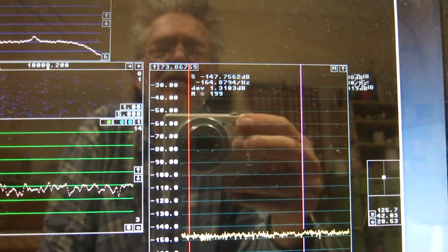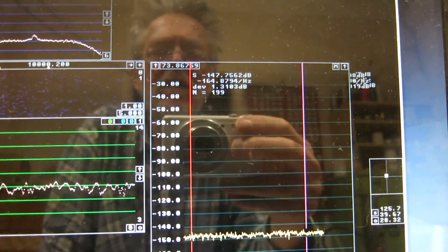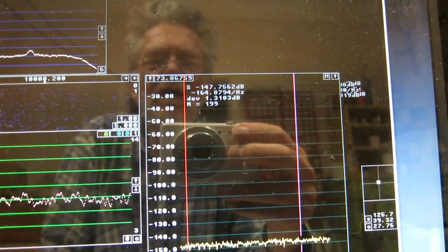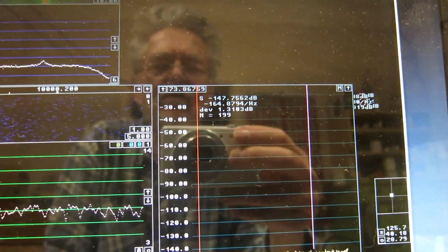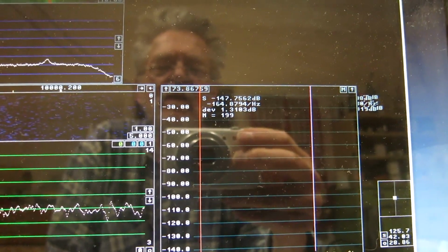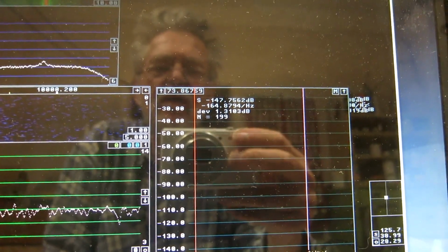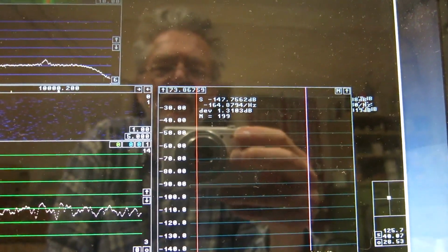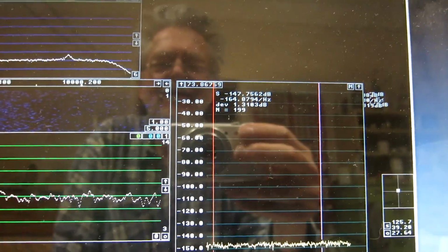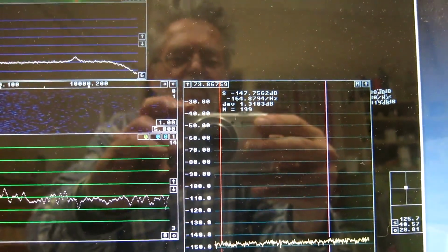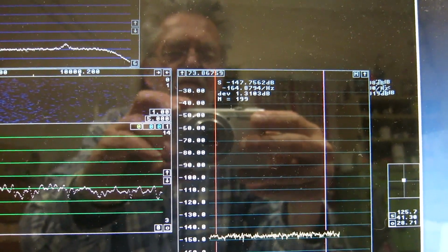So I have gained 1.2 dB in lower noise. And now I should be able to increase the power level of the input by 4 dB. So that's a 5 dB improvement in signal to noise ratio for the carrier, if everything is as I hope it should work. There could be problems from noise in the crystals, for example.